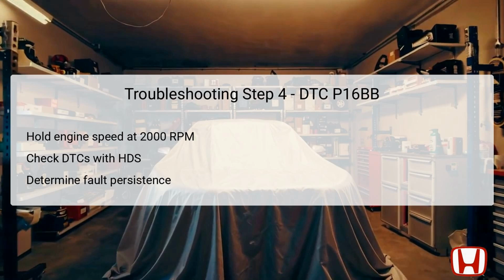If the DTC does not show, it may imply an intermittent fault, therefore requiring additional checks for poor connections or loose terminals that may have sporadically affected voltage transmission.